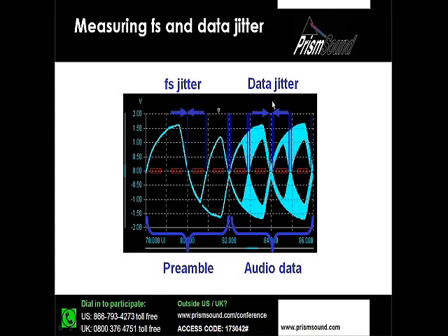Now, keep in mind, data jitter meaning there is audio data inside this bit of the bit stream. Obviously, that's where the name comes from. But keep in mind that data jitter also includes clock jitter. However, since we know what the clock jitter is, we can subtract that from the data jitter and know what is being induced by the cable. Now you can go into your storage scope, or you can put cursors on our D-scope display, displaying this eye pattern, and make those measurements.